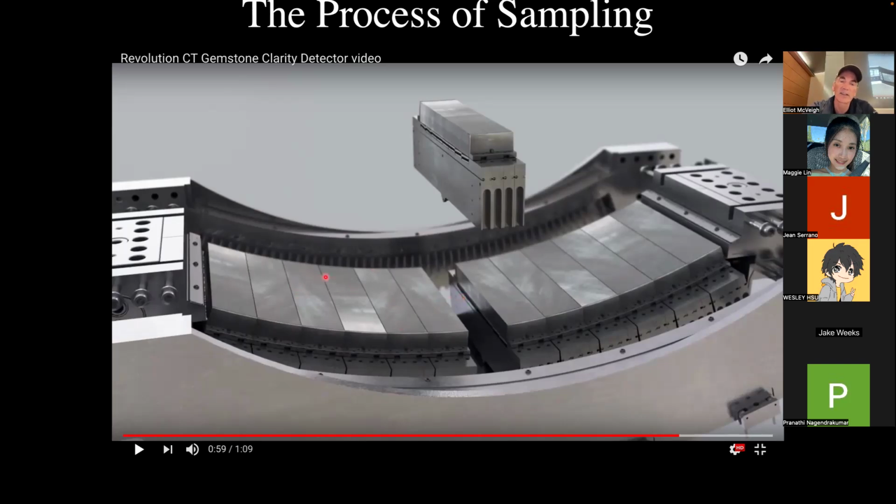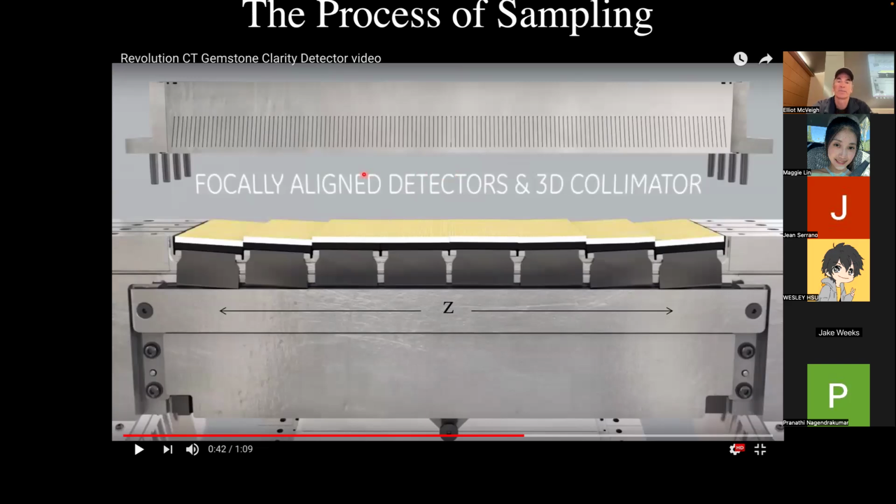And then you can see there are these units, and inside each unit, we have all of the sampling detectors for that band. We're going to open this up right here and look at these sampling chips. This is the anti-scatter grid, and these are the sampling chips. And when I look at that, this is what it looks like: anti-scatter grid lifted off for this illustration, and then here are the sampling chips. Each one of these panels has like 16 by 32, 1 by 1 sampling elements in it, right?